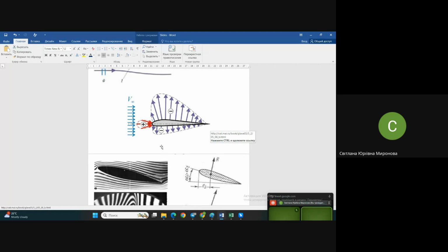Resulting force, and I didn't mention it at least once: the forces we work with, we are talking about, may be, let's say, superficial and volumetric. When it comes to aerodynamical forces, they are superficial. They are applied only onto the surface. Buoyancy force in the aerostatical principle was also a superficial force. Drag and lift are a result of contact of the surface with the media around.